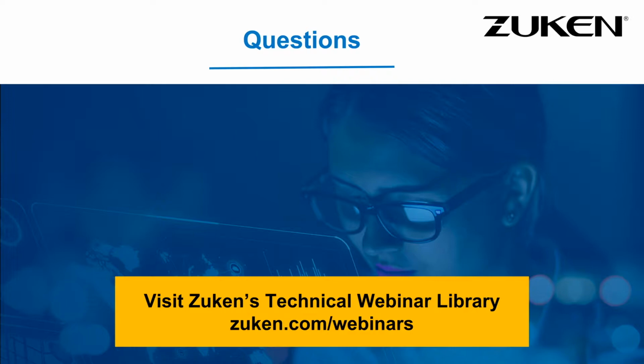We have one from Kevin. Kevin is asking, does E3 support multiple schematic diagrams? Yes. I'm saying yes, but I'm not sure what you mean by multiple schematic diagrams, Kevin. E3 allows you to have many views of the same information. So for example, the schematic diagram could be represented many ways inside E3 series without the information being duplicated. And even the form board was just another view of the schematic information. You can have system level information right on the topology. Everything is interconnected. It's the same model.